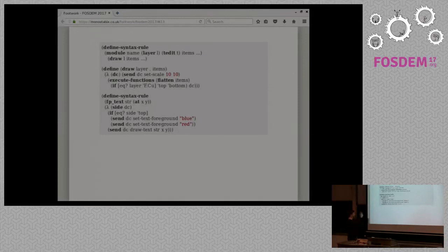And there's a little bit of checking what layer this footprint is on, and translating that to something within the KiCad record code here. So, to clarify, this is what the source of my editor looks like at the moment. This is the start of defining a KiCad language.